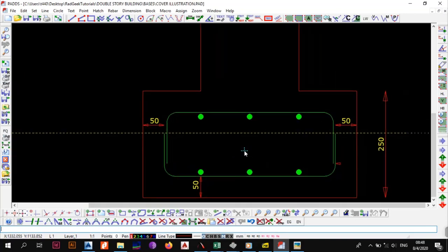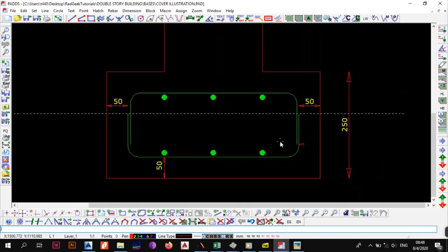So to provide for that, you have to do your mathematics. Say, all right, I need to take off 50 from the top, 50 from the base. So at a minimum, I need a 100 millimeter thick base, but then I need to provide anchorage bars for the top cage and the bottom cage, which is 100 and 100. So you come to 100 plus 100, or you start working yourself. Okay, maybe I need 50 plus 50. So that would give me 200, then an extra 50 to work with.